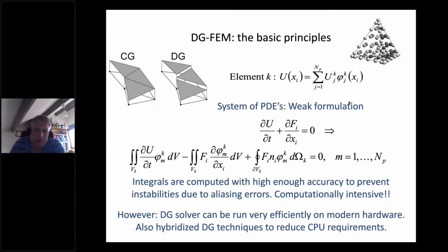What you do typically to obtain high order accuracy in a finite element setting, whether it is in a continuous setting or in a discontinuous setting, is that you use a polynomial expansion inside an element. Typically what you see here is a certain variable that you can vary up to an arbitrary polynomial degree. This is in contrast to what you saw in the talk yesterday on the WENO schemes in the finite volume framework, where you extend your stencil in order to obtain higher order accuracy. You typically do not do that in a finite element framework. There you increase the polynomial expansion of your problem.